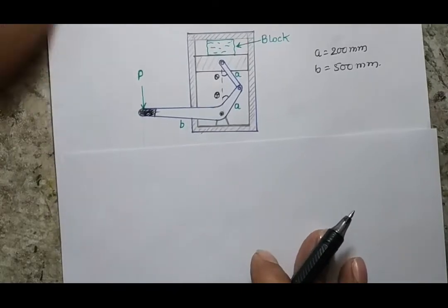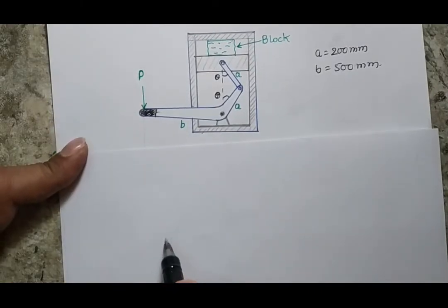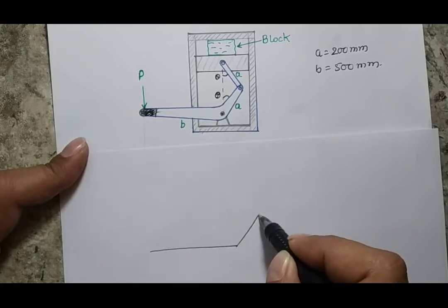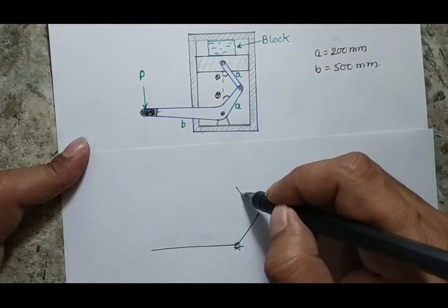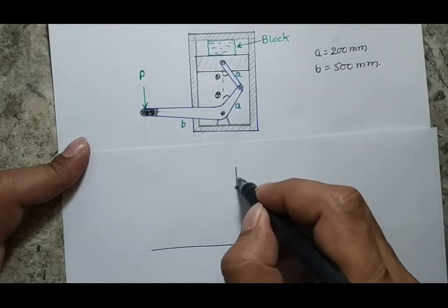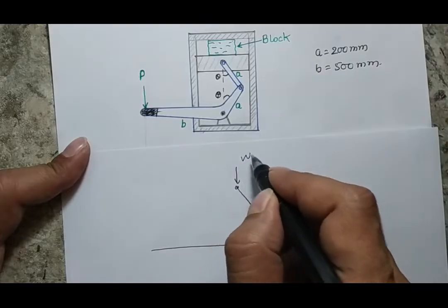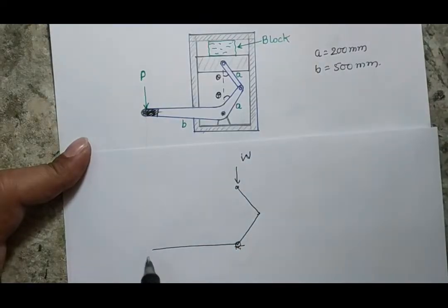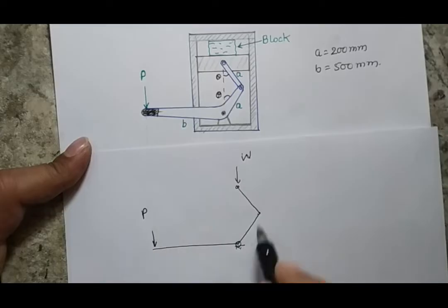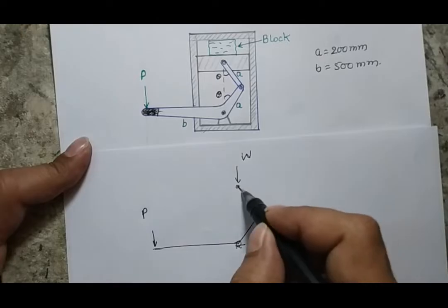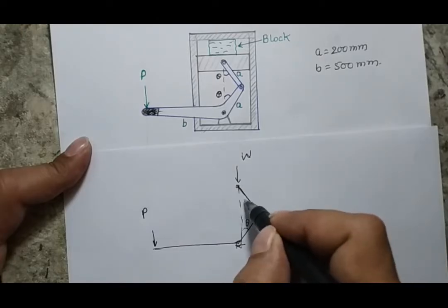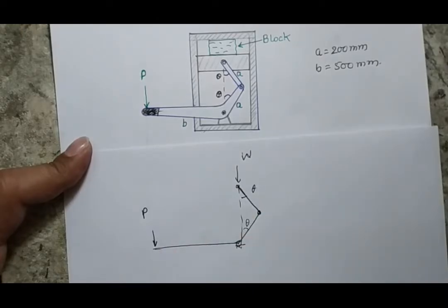After understanding the degree of freedom, when you apply the principle of virtual work, your second and immediate job is to make the free body diagram of your system. Here I am making a free body diagram considering the lines. This is your first fulcrum part, which is pinned at this point. This is your second link, and there is a force of W because of the compression of this block. I am not drawing the piston and other things. This is your W and this is your force P. Now this is your link 1 and this is your link 2. Both have angle theta at this stage, and the system is in static equilibrium.